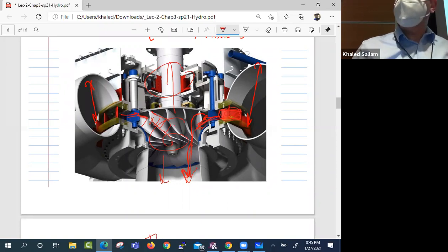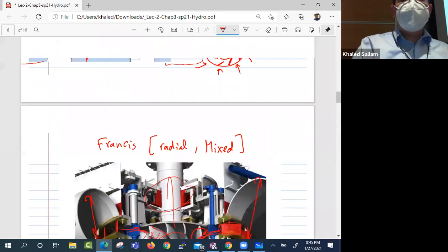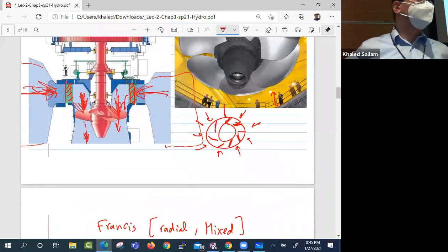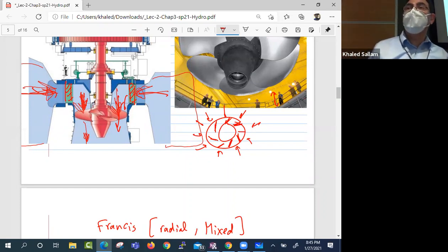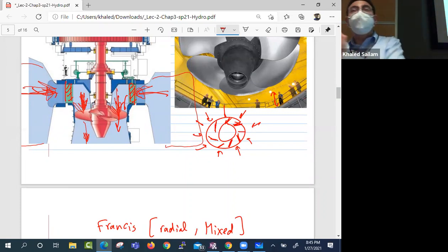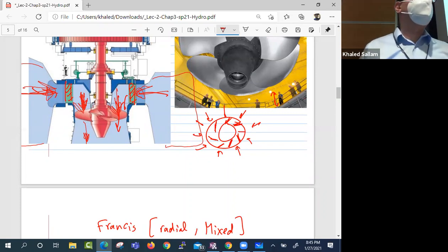The radial machine. A radial machine can have a huge pressure drop because you can see how they have tight passages. You can really control the pressure. But the axial one is almost open, so you can handle a lot of flow rate in it. And that's the same for the jet engine too. Axial compressors can have huge flow rate but small pressure rise. That's why you see so many stages, because each stage has a little bit of pressure rise. But radial compressors have a huge pressure increase across them, but very small flow rate.